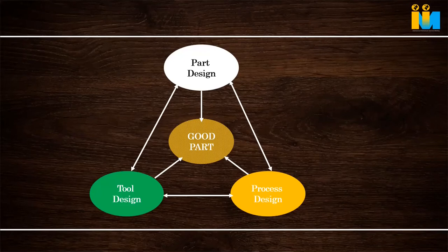So as a designer, we have to know before making the part, we can do some mold flow and whatever we can do, and use all our experience. And the tool maker should also understand the gate freezing study, pressure drop study, temperature drop studies, and shear rate studies. If we have done everything, then it will be easy for the molding person to process the part.